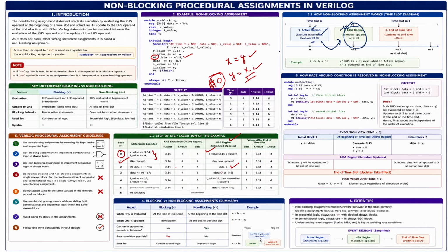The same values will be displayed here because $monitor continuously captures whatever values you change. $display just displays whatever value you are displaying at that moment. But when you use $monitor, it always captures the changes. Whenever you change the input values, it will be captured. That is the purpose of $monitor in your non-blocking assignments.